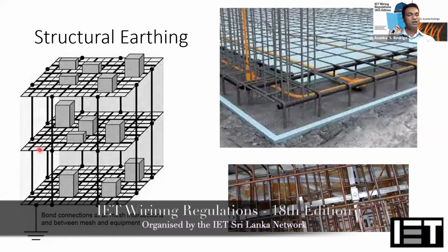So the concept is this type of three-dimensional earthing arrangement where all the floors are connected together, the foundation is connected together, all the equipment is connected together, so that even when there is a lightning discharge, they will travel and everything will be at the same potential. Keep in mind the damages always happen when you have a potential difference. If you are keeping everything at the same potential, damages are not happening.